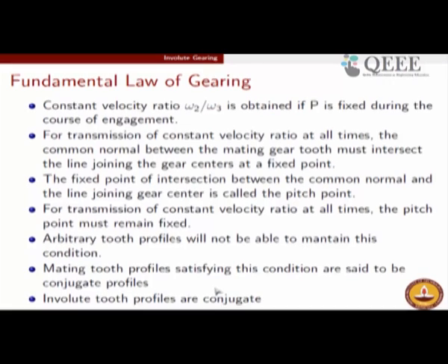One reason for the involute tooth profile is that we will see it is always able to satisfy this condition of the fundamental law of gearing. There are other conjugate tooth profiles, for example, cycloidal tooth profiles are also conjugate, but involute tooth profiles have many other advantages other than satisfying the fundamental law of gearing.